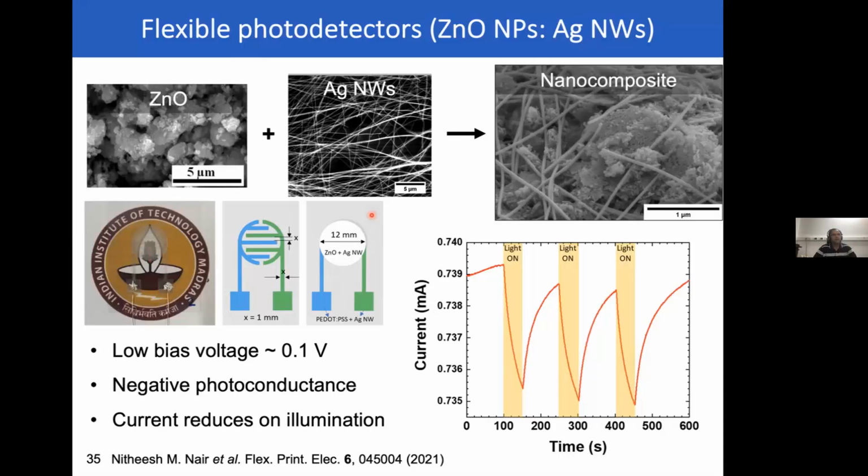So the yield, I don't have the numbers. I know polyol is not great, but hydrothermal has, I think, a better yield than polyol. But again, I don't have the numbers off the top of my head. On the second question about PVP, it is still there in the dispersion. But normally when we print or deposit it, we typically anneal it at around 100 degrees C. That gets rid of the PVP. But we don't do anything else specific.